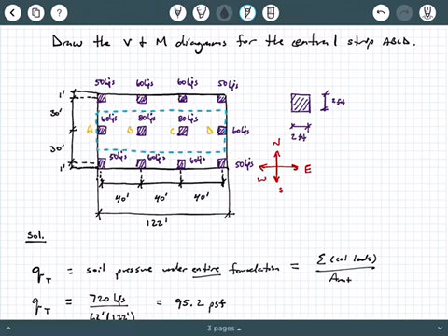Once you design that for all the reinforcement, then you can take what you've designed for that central strip and then just repeat that same reinforcement scheme for the edge strips on either side of it. Okay, now in the actual design procedure, you want to do this for both primary directions.